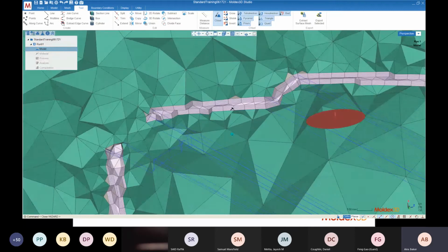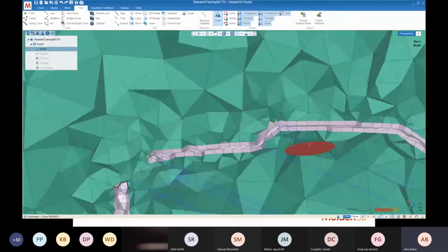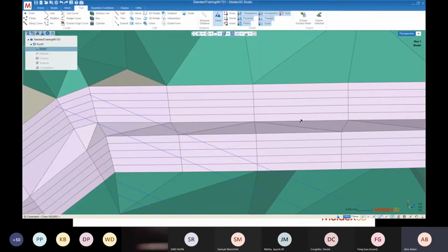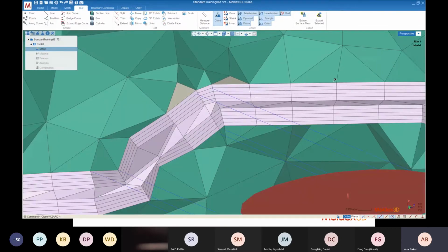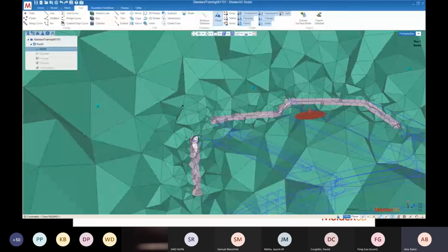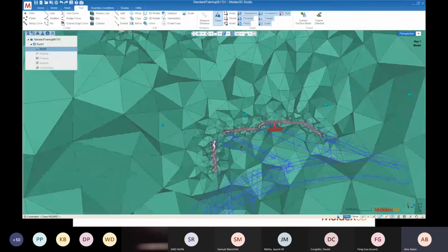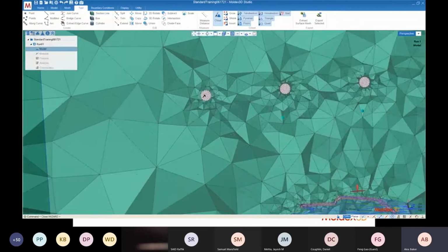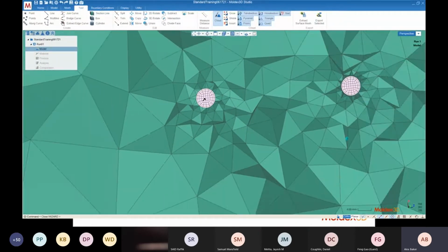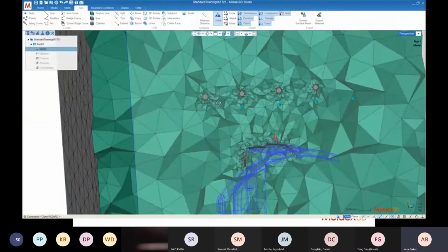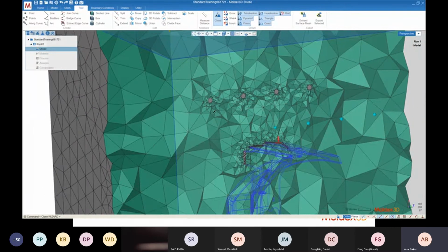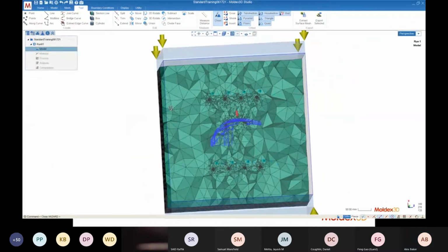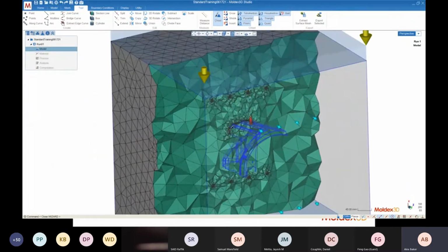Then I can zoom in to see what kind of mesh was generated. So we can see that 5 layers of BLM were generated here, 5 on the top, 5 on the bottom, and then our tetrahedral layer through the middle. We see that pure tetrahedral mesh for our mold base. And we have our cooling channels over here. There are these hexahedral elements that are perfectly consistent along the line. All right, very, very high quality mesh.